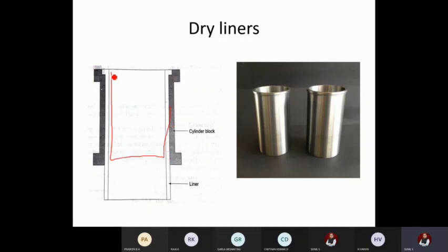If there is a direct contact between the piston and the cylinder, after a certain period of time, the cylinder or the piston may get worn out, so the gap increases. When the gap increases, what happens? There will be a leakage of gases. You can see some black smoke in some of the old trucks. When they accelerate, there is more black smoke. So what is it? The uncombusted fuel particles just escape from the gap. In such cases, they will go for reboring. Reboring is a technique where you increase the diameter of the cylinder by machining this surface and going for a new piston with a higher diameter.